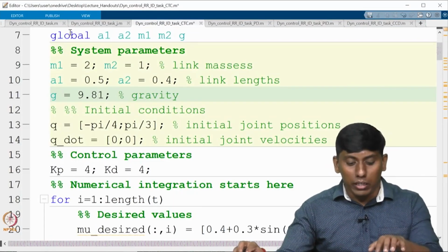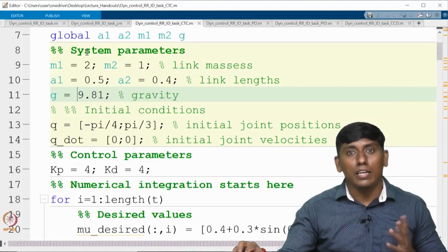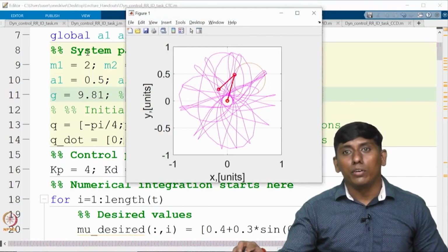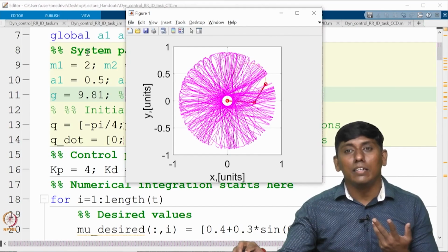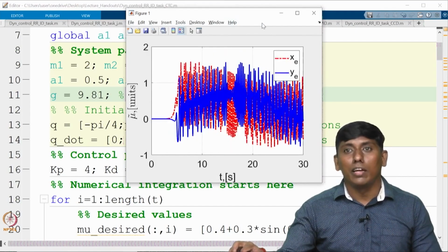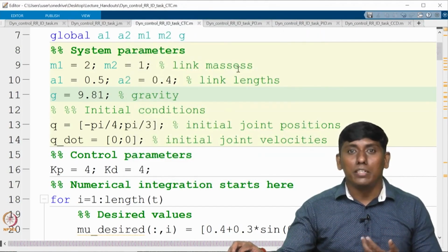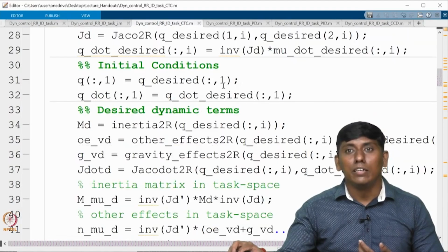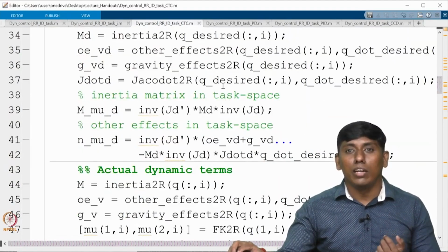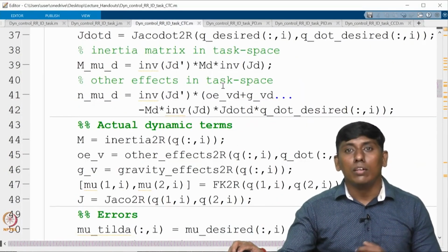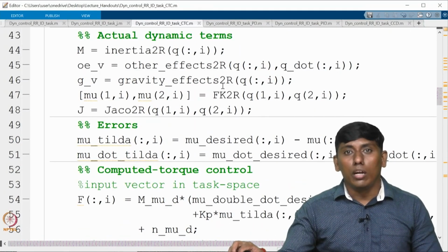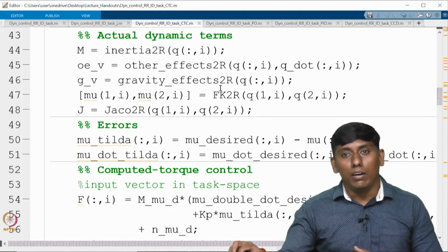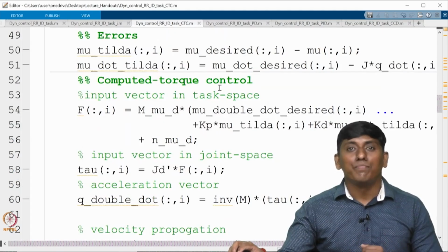So now I include the gravity, and you can see the error may be the same order, okay. Now you can see we have not compensated that directly, right. That is what I want to show. We have not compensated that gravity here anywhere. Because of that, it is giving an additional adverse effect, okay. So now you have an idea why we need to account for this, right.